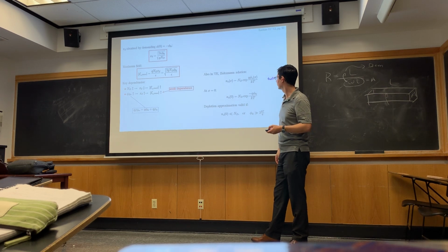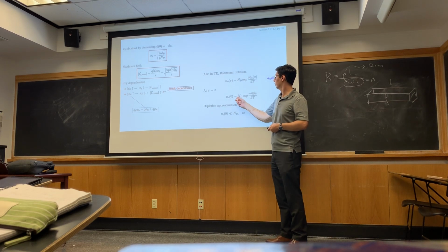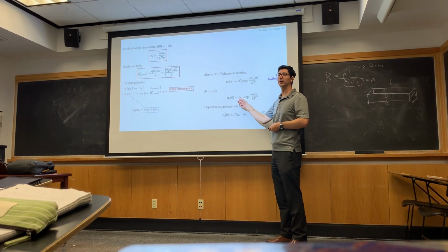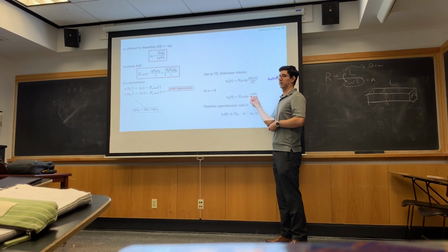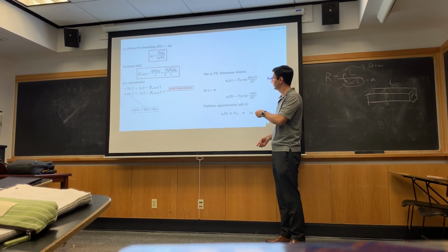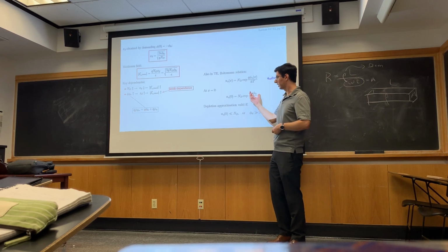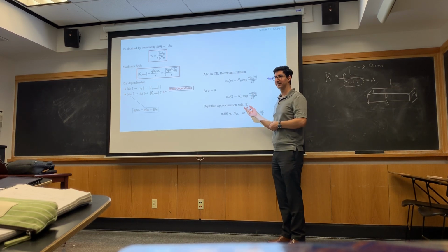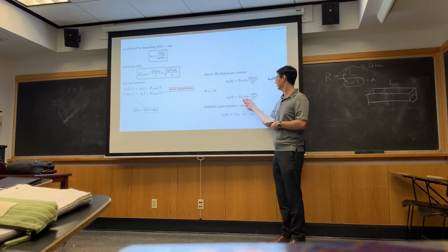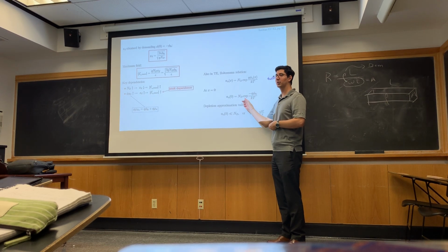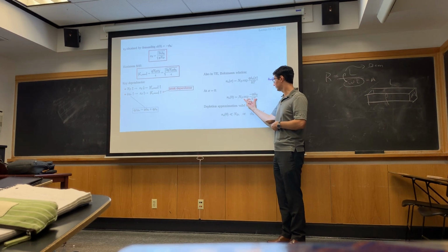But we know we're depleting electrons, right? So I can calculate, I know what my carrier concentration is in the bulk. How much did I change my potential by? Q phi bi, or phi bi. And so I put it in this form, and that's where my carrier concentration is at the surface. This is the same thing. If phi bi was 60 millivolts, this would give me 1/10. If phi bi is 120 millivolts, this term right here would give me 1/100.